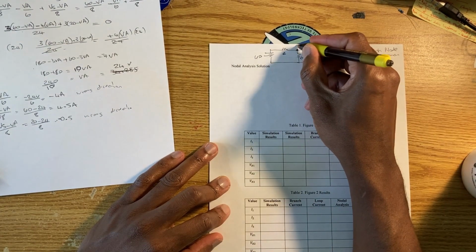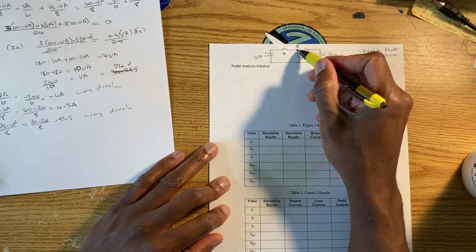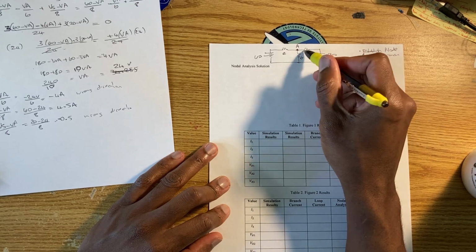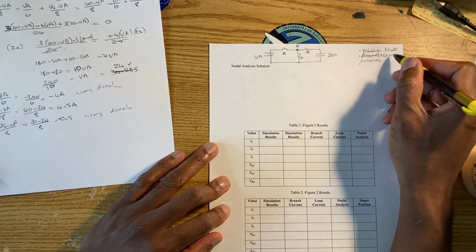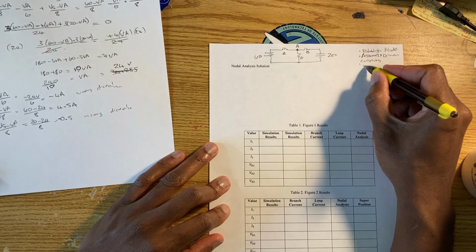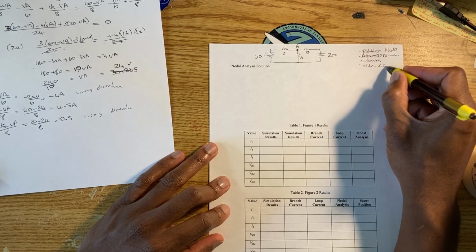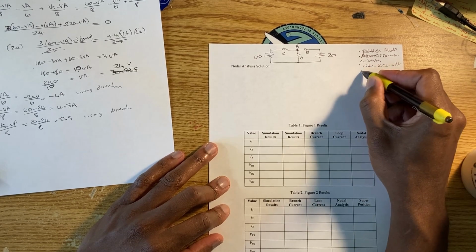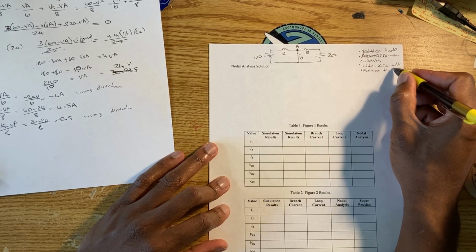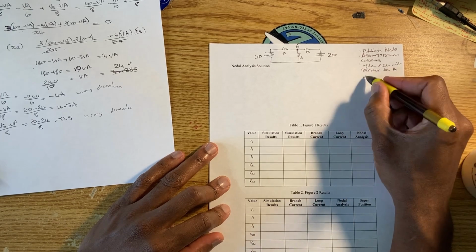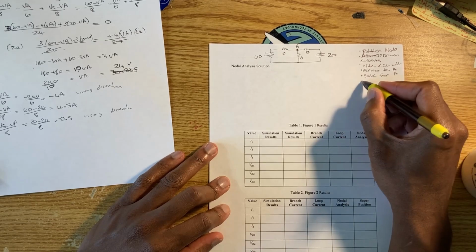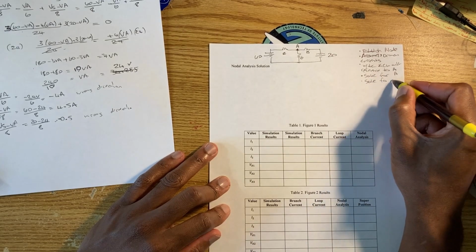So I'm going to call this point A. So I'm saying that the voltage at this point is A. That's the same voltage across the 6 ohm resistor, the voltage if you minus the voltage drop here or the voltage drop there. So this is the branch, assume branch currents. Then we're going to write the branch currents with reference to A. Write the KCL with reference to A. And of course, then we will solve for A, and then we can solve for currents.